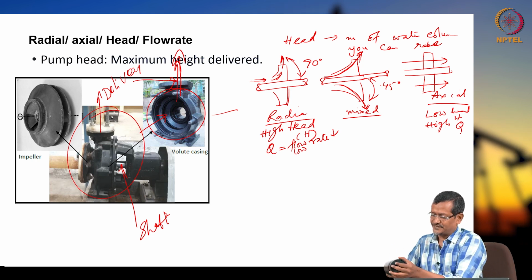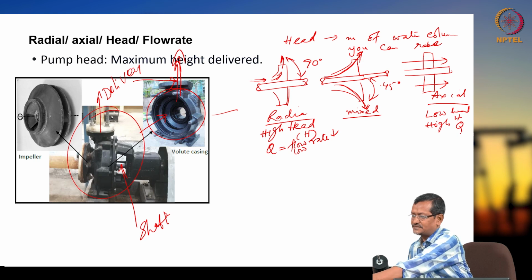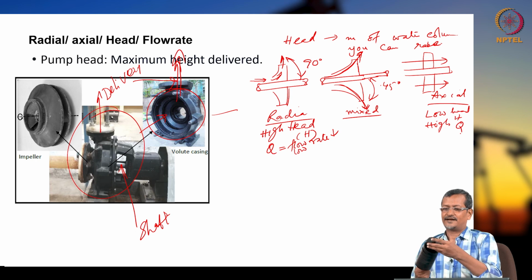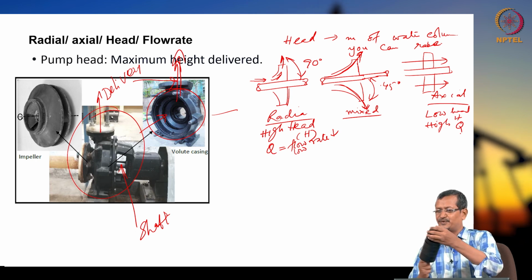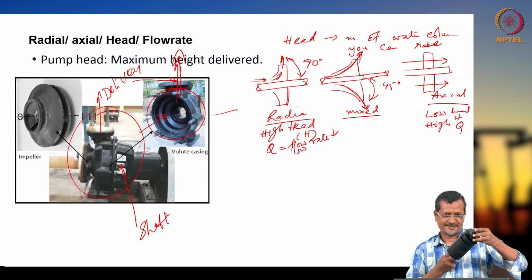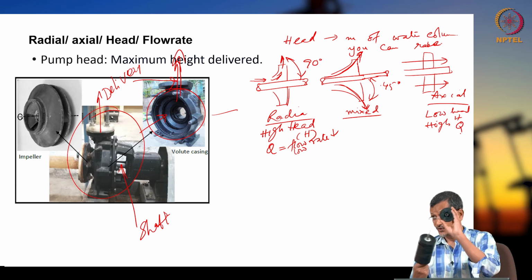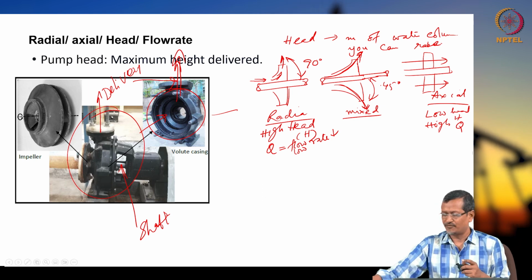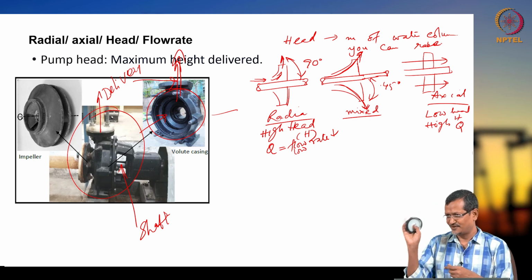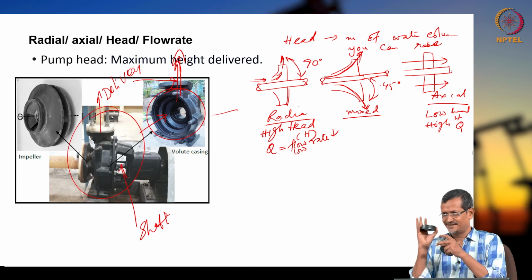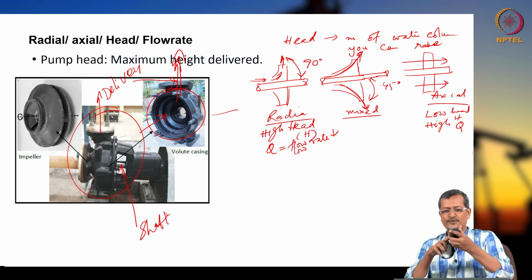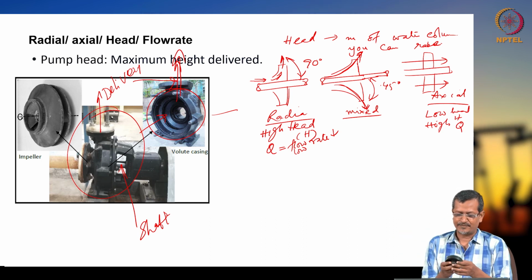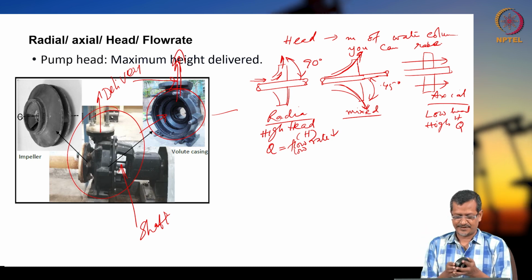Okay, again you see this design is such a way, and this shaft is designed such a way, that when you put it, there will be no relative motion. So, if I rotate it, the impeller will be rotating. This is called the rotor, and the casing or volute casing, this part is the stator, not rotating. It is fixed on something and held, and this rotates. When rotating, it gives high velocity fluid, and this will reduce the fluid velocity. So, together they become one stage.